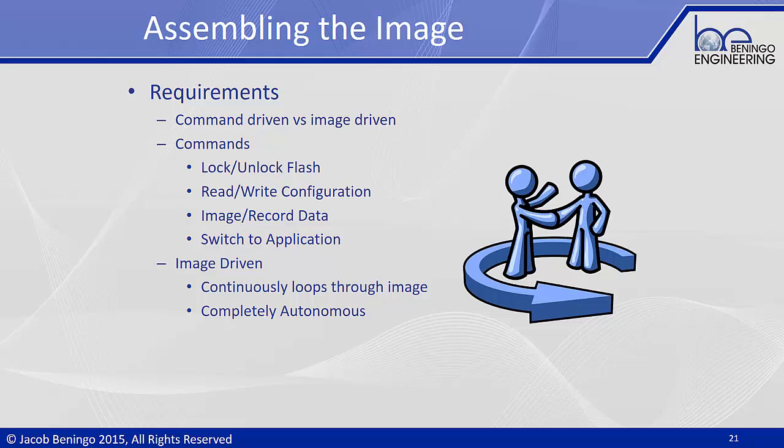Now, one of the purposes of the bootloader, the primary purpose, is we really want to be able to take application code and update it on our microcontroller. As we talked about before in the requirements section, there's a couple different ways we could go about doing this. We could have a command-driven bootloader where we have the server or some type of laptop and a GUI driving the process to update the firmware. So it may be sending a command to erase, sending a packet of data over, waiting for acknowledgement, sending another packet, waiting for acknowledgement. Or it might be totally image-driven.